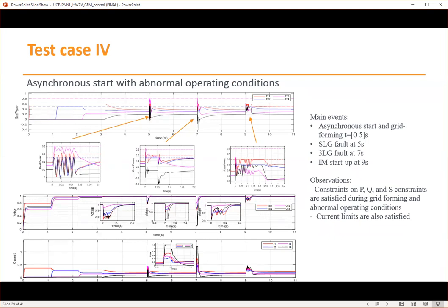What the plot is showing is that with constrained control, you can impose not only the maximum output power each of the DGs can provide dynamically, but also, as the fault occurs, the current would be limited, and that provides much better ride-through capabilities for the inverters, which ensures the appropriate operation based upon the IEEE standards.